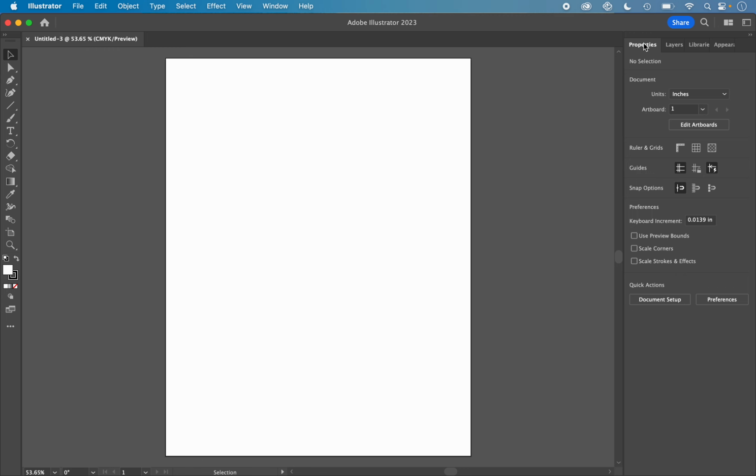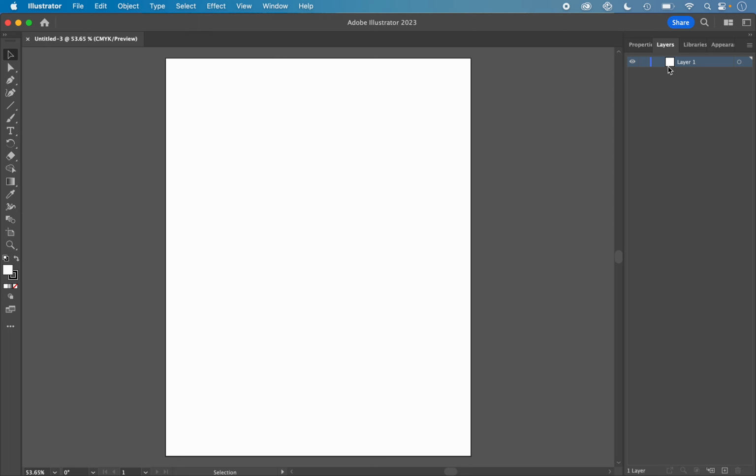Now over here under the Properties and Layers, we'll click on the Layers tab, and it defaults to one layer, but we'll come down, click the plus sign twice to get 2 more layers, and just click and drag that green layer to the bottom. We want to use that as our drawing layer. So we'll double click there and type in drawing, and let's go ahead and name the blue layer cut and the red layer score.